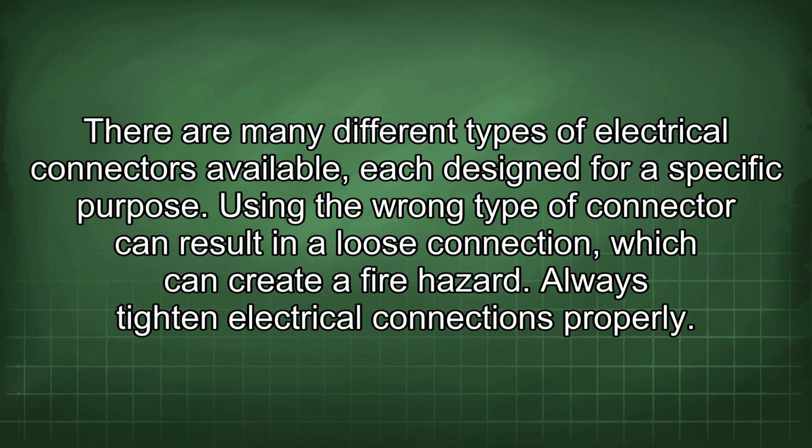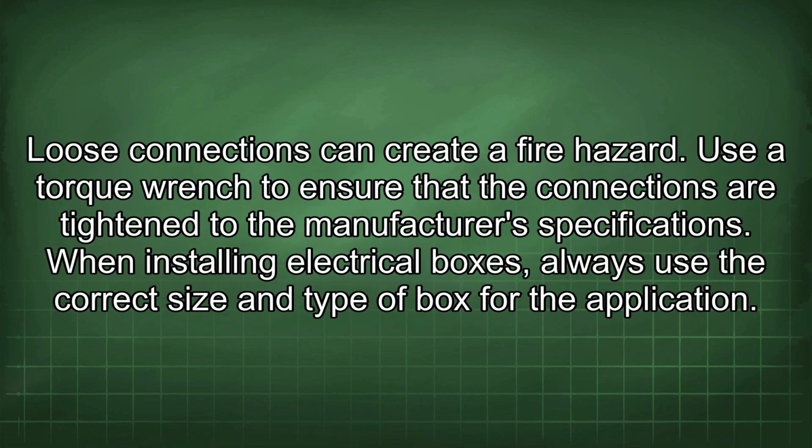Always tighten electrical connections properly. Loose connections can create a fire hazard. Use a torque wrench to ensure that the connections are tightened to the manufacturer's specifications.